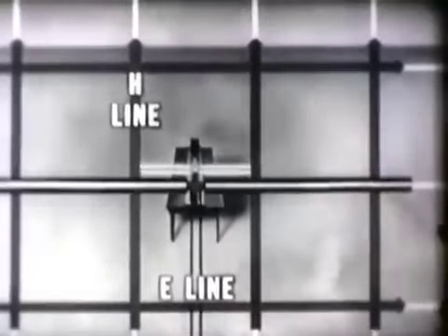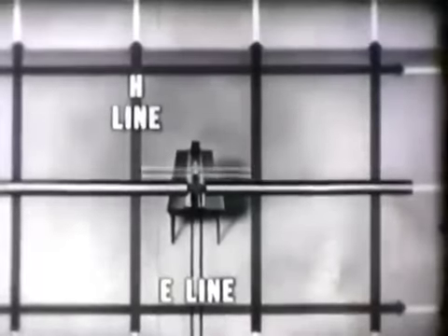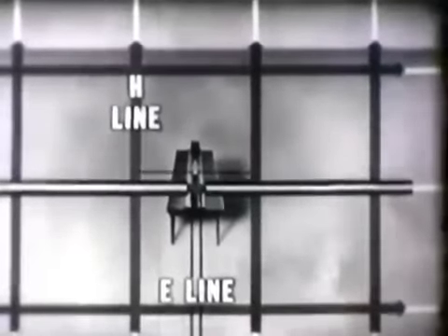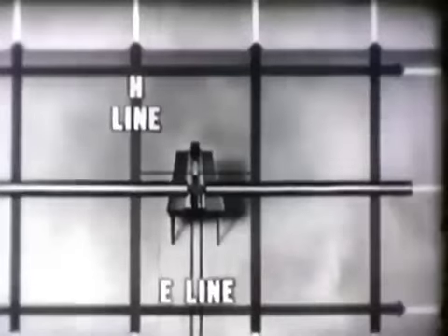The transmitting and receiving antennas are now parallel and broadside to each other. This broadside position is necessary because of the nature of the radiation pattern of the half-wave antenna. The shape of this pattern indicates areas of no radiation or nulls along the axis of the antenna. A receiving antenna placed in a null area would be unable to receive a readable signal.